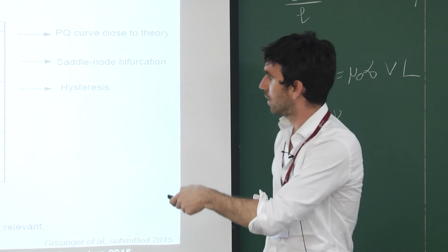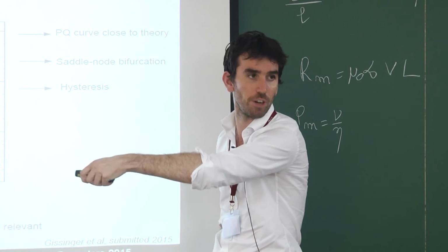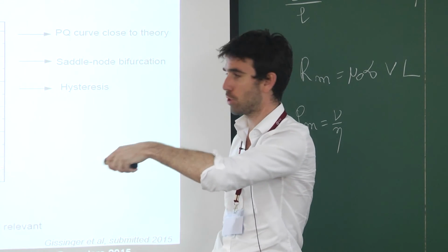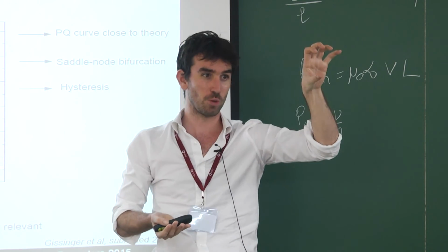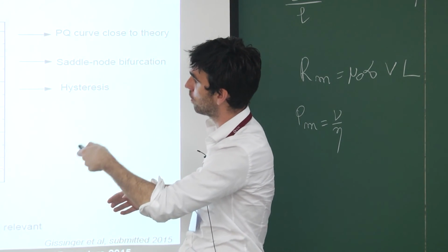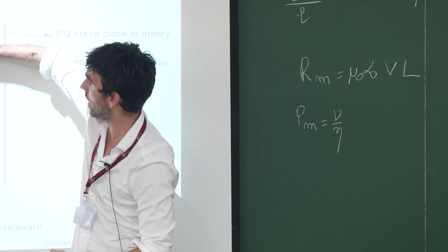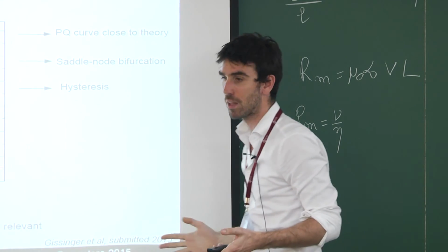When you increase the pressure gradient, you have your viscous dissipation, which is the red curve I showed you. When you increase the pressure gradient, this red curve is moving up because your dissipation is now the viscous dissipation plus the pressure gradient force. And by moving up, you see what happened. You go there until you reach this point, and then you stall like that. So it's exactly the same mechanism.